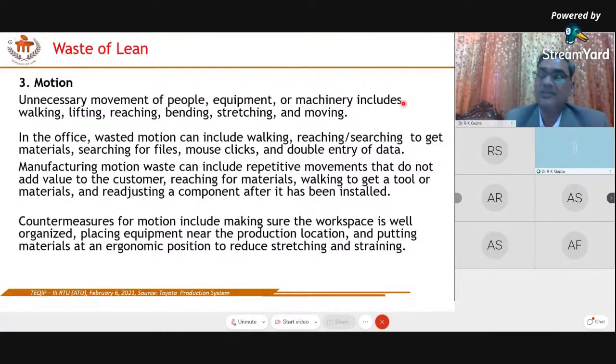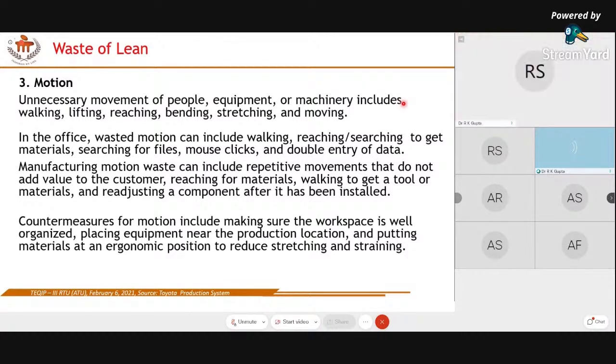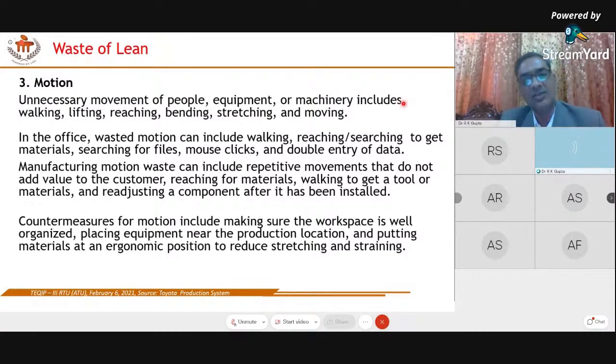So that's why the key machine concept is also involved in this. There's one machine which is very expensive, or performs certain critical operations. Take the example of a CNC machine that performs some critical operations, or the vertical machining centers or the horizontal machining centers. So these are the critical, expensive machines which perform the critical operations, and the other machines are supporting these machines. That we call the key machine concept.